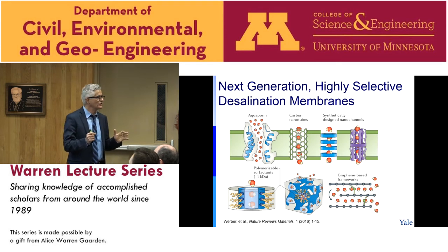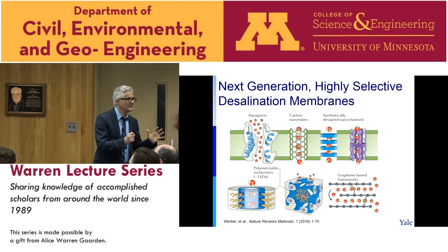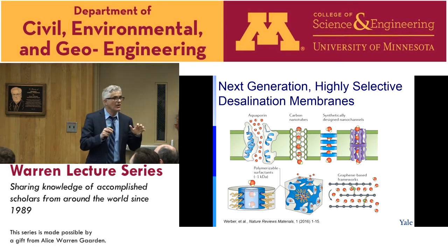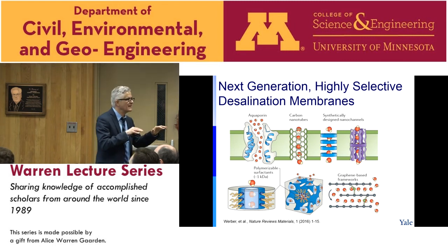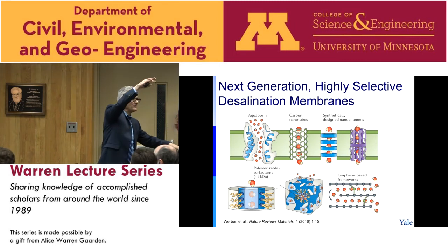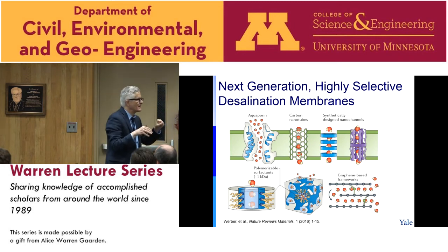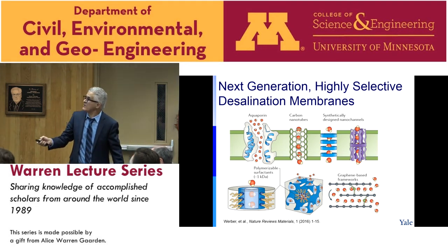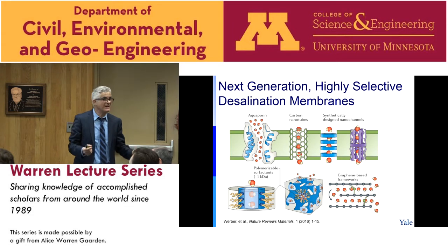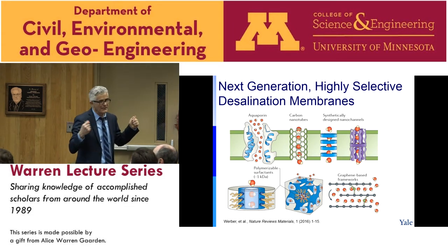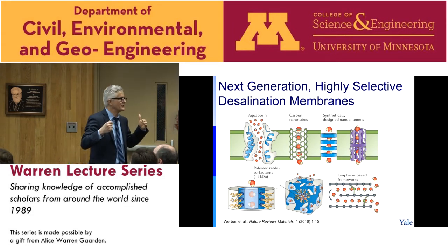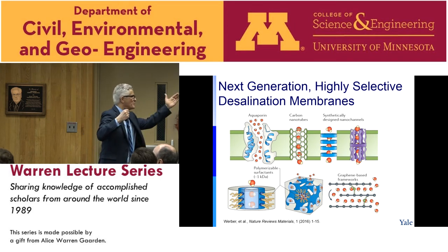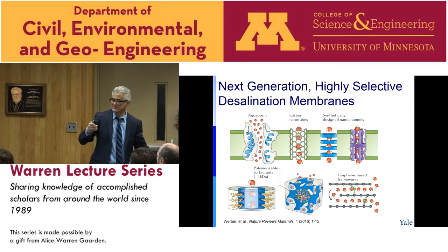What are the next generation membranes? In my opinion, they should be highly selective, and membranes that operate in a way different from the current membranes that operate based on the solution-diffusion mechanism. This solution-diffusion mechanism bounds you to this permeability-selectivity trade-off. And we discussed aquaporin membranes and carbon nanotubes earlier, 10 years ago, and even now you can see some papers, we're still trying to push for high water permeability, and I showed you it's not important.